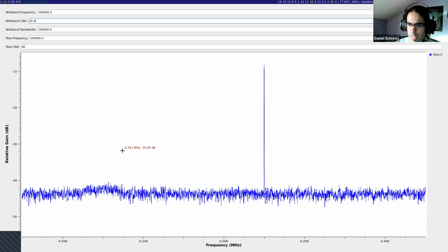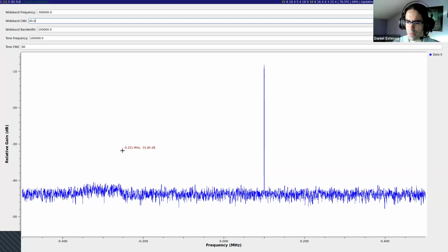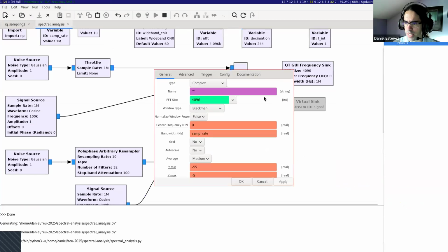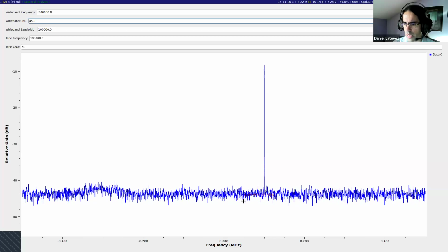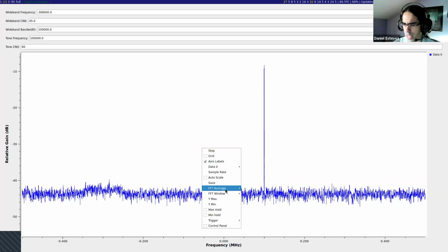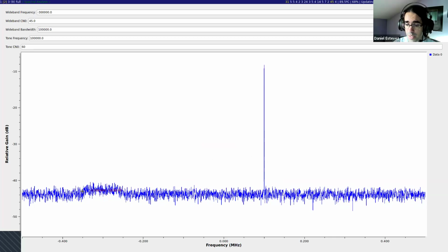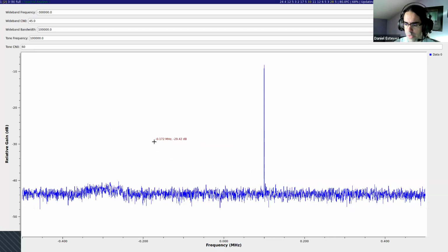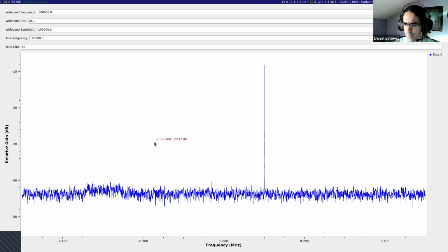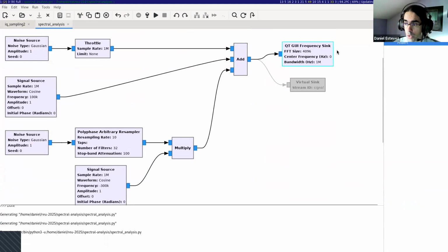so the next thing I want to do is to do a better spectrum display. Because to be honest with you, this one, which is the default frequency sink, is not very good. We can see that the noise floor is still moving, even though I have the average set to high. And that means that there are some weak signals we cannot detect with confidence. So we can do better by doing something like this, but by hand. And by doing so, we can also learn how this block works, because we are going to do something very similar but using multiple blocks.